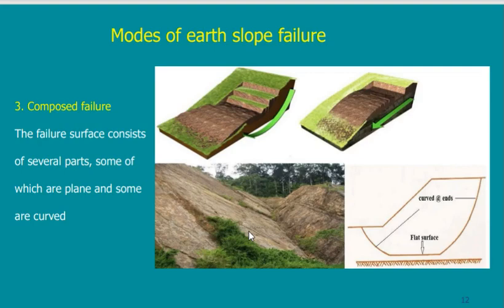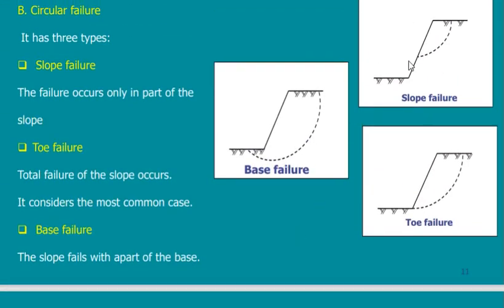If I come to this one, what are the forces that are causing shear stresses? It's the own weight of this slope. It's any external load on top here. It's the water if it is moving, seeping here. All these forces, I will get their effect, and I will tell you that there is a stress of a specific value acting on this plane. This is the first part.